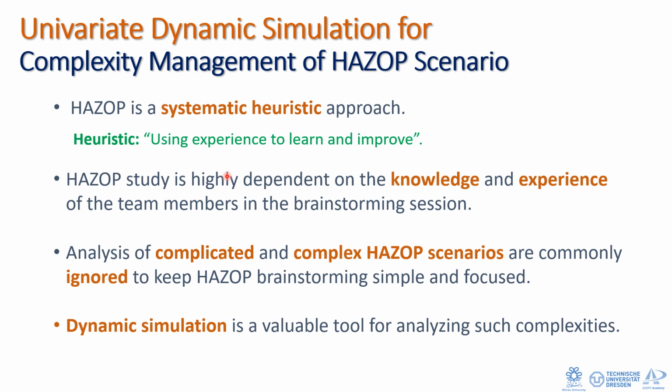Subjectivity is another weakness of HAZOP studies. The quality and resolution of HAZOP studies is highly dependent on the knowledge and experience of the HAZOP team. A given case can be assessed very differently by two different HAZOP teams. The subjectivity of engineering judgment of the HAZOP team can be improved by providing the relevant checklist, standards, lessons learned, etc. to them.